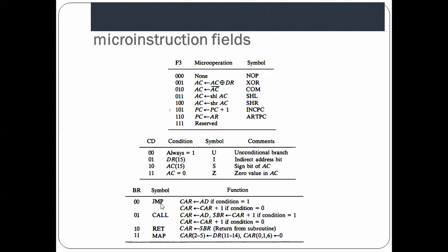For example, once you complete one particular instruction execution, you have to proceed with the next instruction. The first micro operation is related to fetch, so you need to jump to the fetch routine. It is a permanent jump; you don't need to come back to this subroutine again, so you don't require return address storage. In that case, this type of branch is jump.